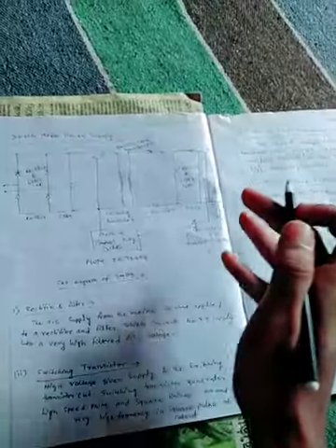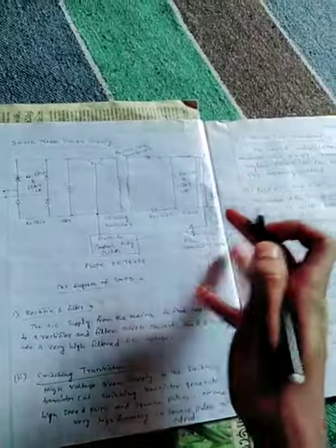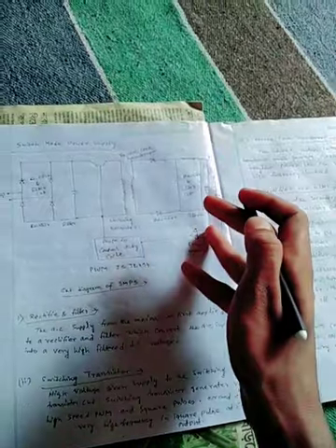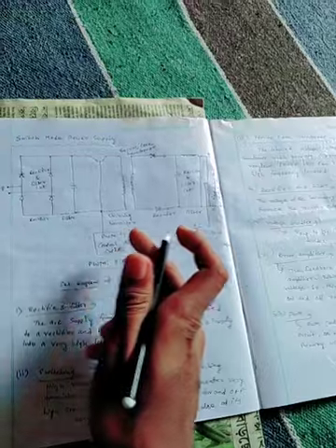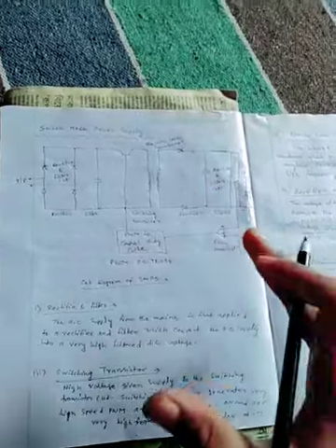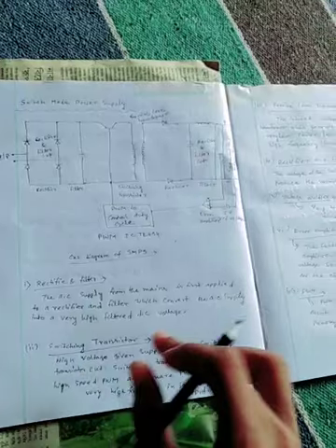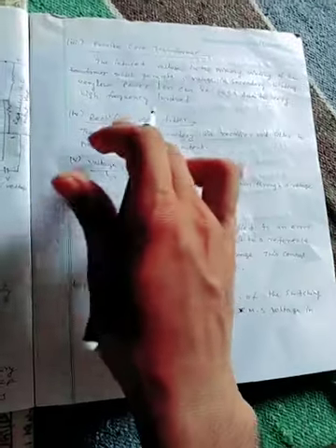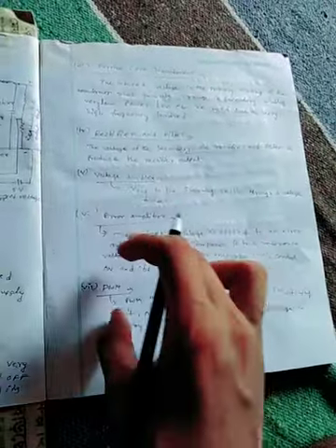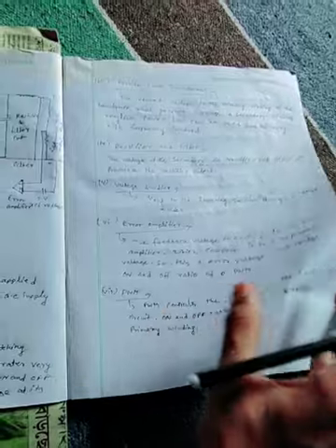This is the 5 volt reference voltage. This is the error amplifier, and this voltage goes to the PWM to control the on and off of the circuit. This is the rectifier, the switching transistor, the ferrite core transformer, the rectifier circuit, the secondary voltage divider, the error amplifier, and the PWM, pulse width modulation.